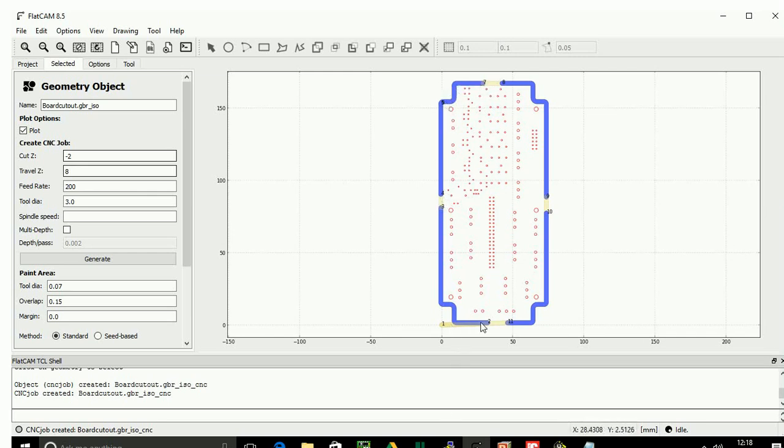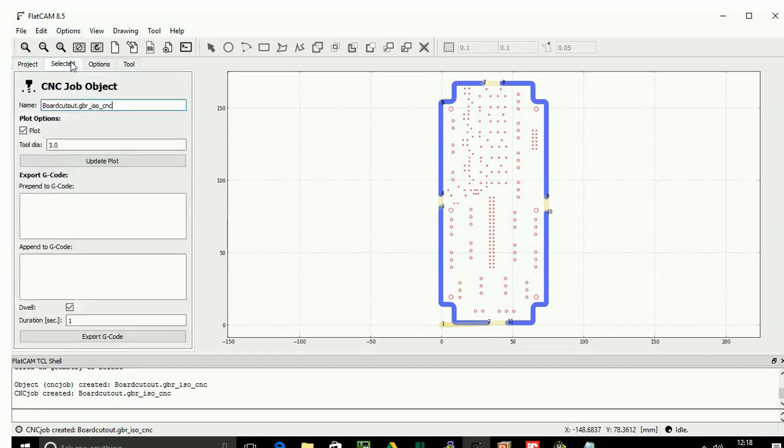So come here, go to. You will see the position. They go to number 2, go like that. Then come here, and so on. So now we need to generate the G code for this. So as before, put G00 Z10, then G00 X0 Y0, and the same thing, but I need to change it up here.